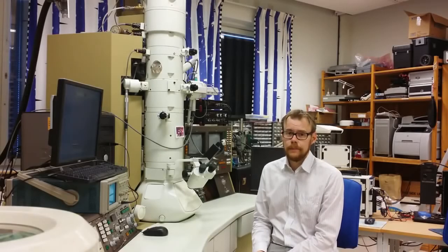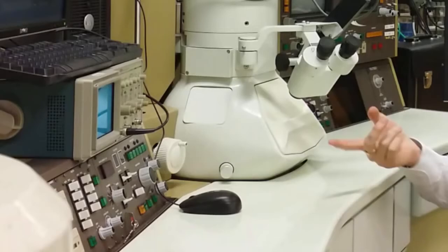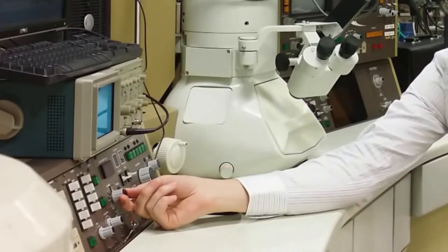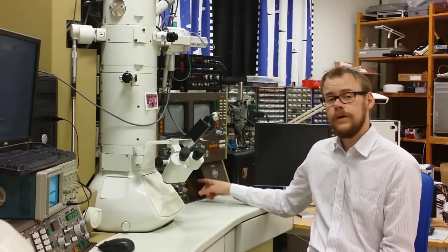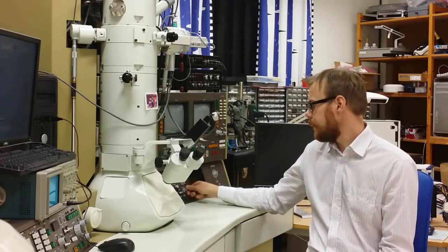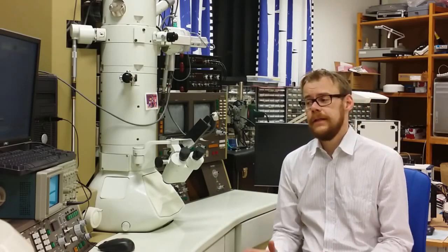Now I have turned on the lamp again and put back this protective cover screen. So how to shut down the microscope, you basically do the reverse procedure of starting it. So first you turn off the filament. After that you go down to 150 kilovolts in accelerating voltage. Then you turn off the high voltage. Turn off the computer screen. And that's it. Then we are ready for the next